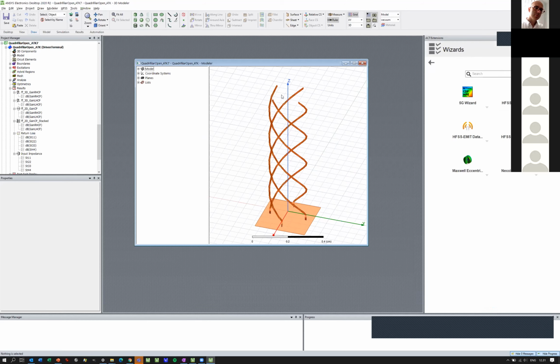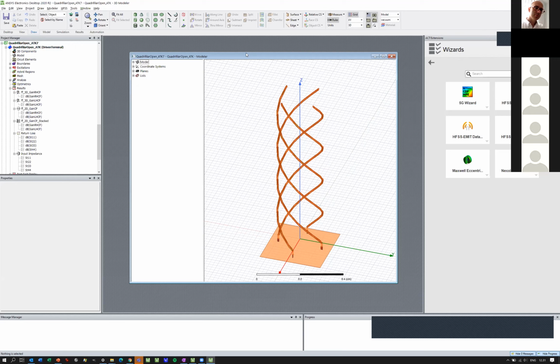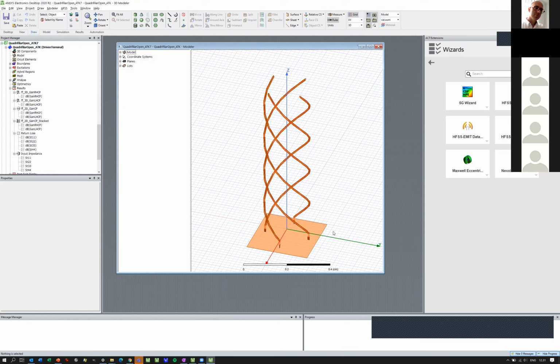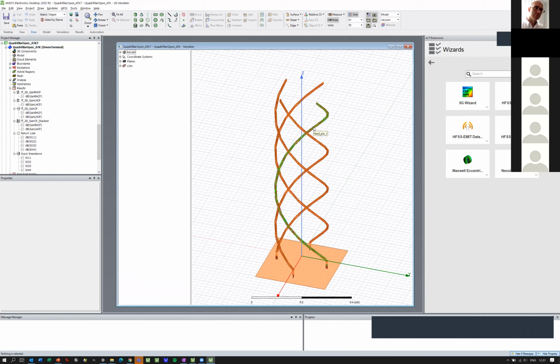Why are these kinds of antennas interesting? Think about airplanes, or especially satellites, which are moving, rotating. This kind of antenna has a round face, so it doesn't really depend on the rotation, the polarization is rotating, so you will always get the same signal amplitude whatever rotation phase this antenna is on the satellite.